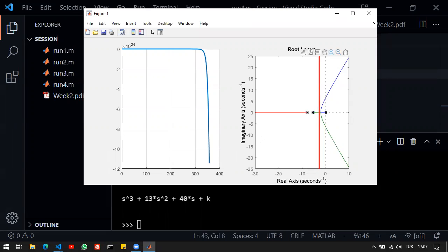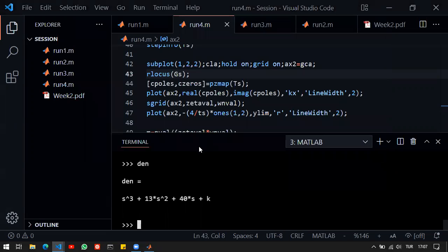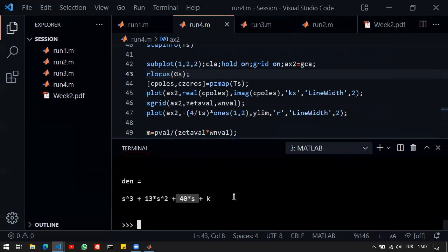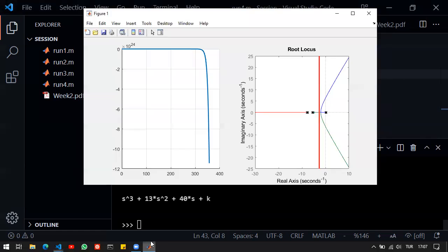And the reason behind that is the fact that omega n is not real in the coefficient method here, or the algebraic method, as we call it. Here, omega n is not real, so there's no solution where omega n is real. Therefore, we cannot design such a controller. Or if you look at the root locus, we can see and conclude that it's not on the root locus, therefore it's not achievable. So that's pretty important.